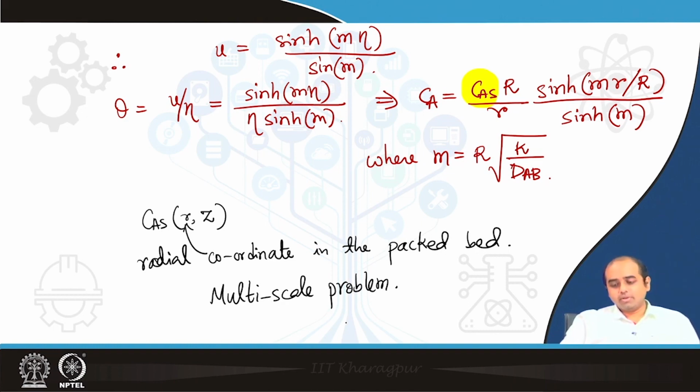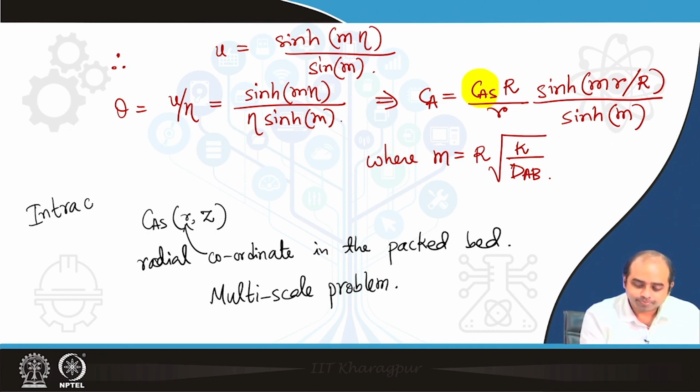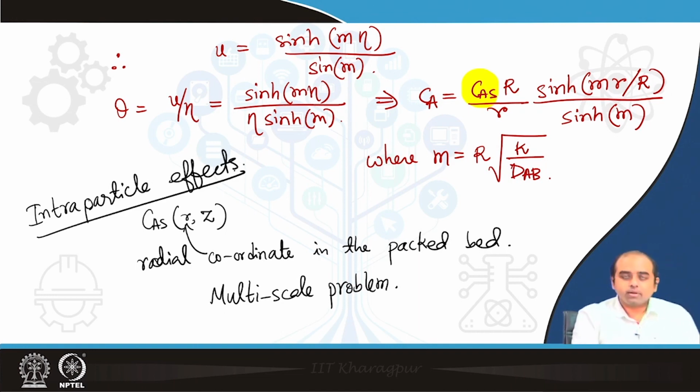But essentially this is a multi-scale problem, and this is also very similar to a packed bed adsorption column. So, I hope I could give you a nice flavor of this very important packed bed reactor and how the intraparticle effects are coupled in this problem. So, the transport inside the particles needs to be computed and can be hooked up to the bulk or macroscopic calculations of the packed bed.